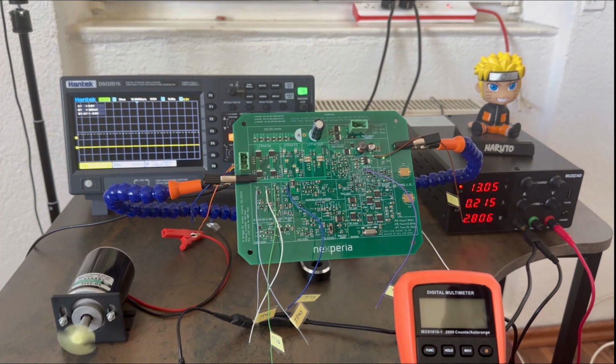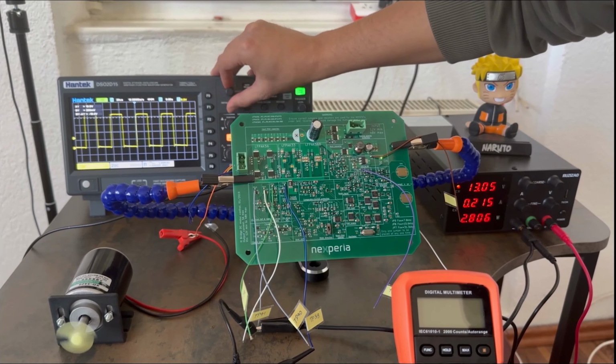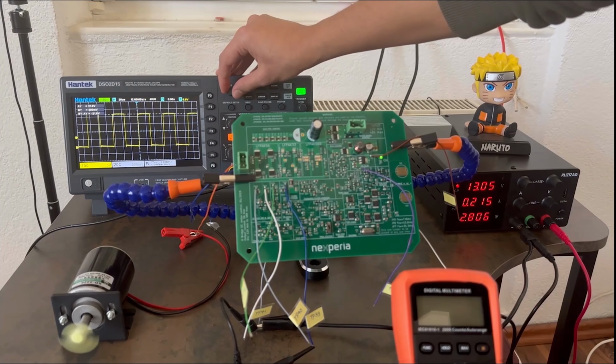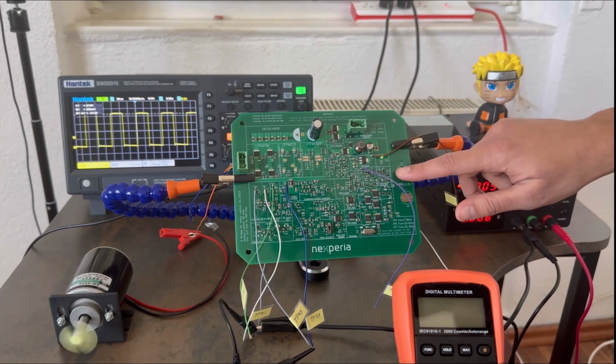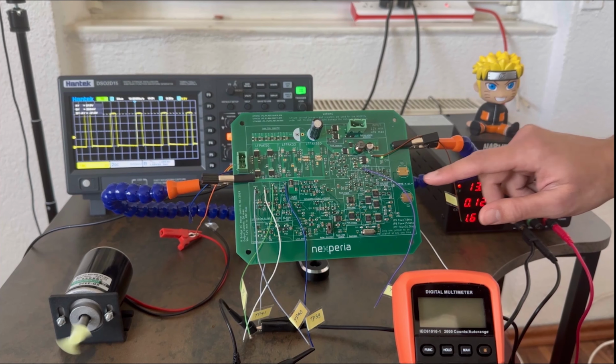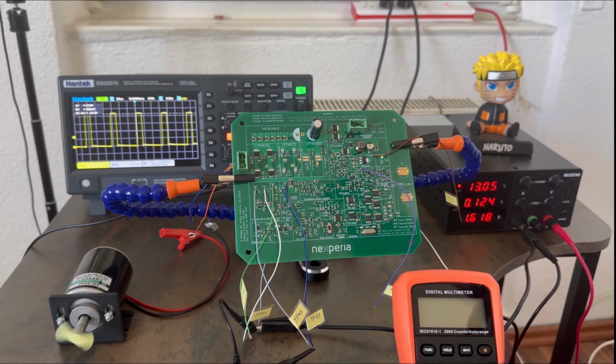Well, if the motor is running in the reverse direction, that means Q1 should be turned on with PWM. Let's see that as well at test point 39. Cool, we can see the PWM across Q1. And its voltage is around 21 volts with respect to ground because it is a high side switch. Again, if the speed changes, the duty cycle of the PWM changes with respect to speed. Well, that's how an H-bridge motor driver works.